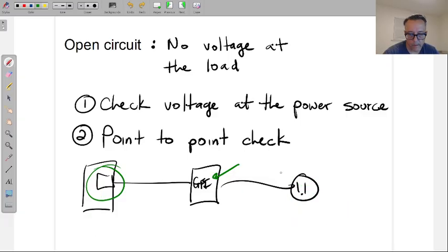Residential, it's a really good idea, especially these days. Start thinking GFCI immediately. Now, older homes too, you can also think switch, right? Switch on the wall. Usually people know that they have a switch that feeds an outlet, but maybe not. Newer home, they haven't gone through everything. You're there because they are going through that punch list. They just moved in, they can't get this outlet to work, and you figure out that one of the switches on the wall is the one that turns on and off the outlet.